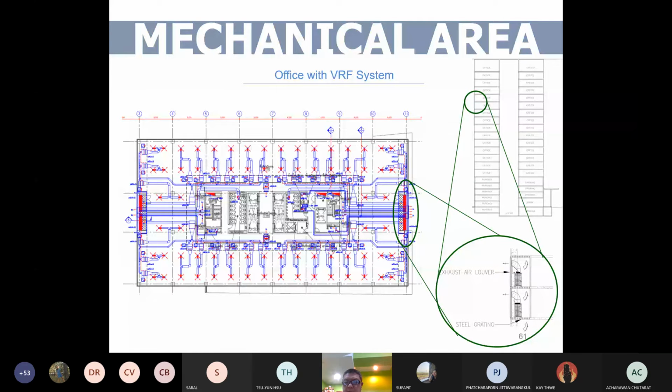In a very high building, as I told you in the story, sometimes wind blocks the condensing unit so it cannot reject the heat out of the condenser. So it will create a problem. When you design this, you have to go to the job site yourself and make sure the air is not blocked.